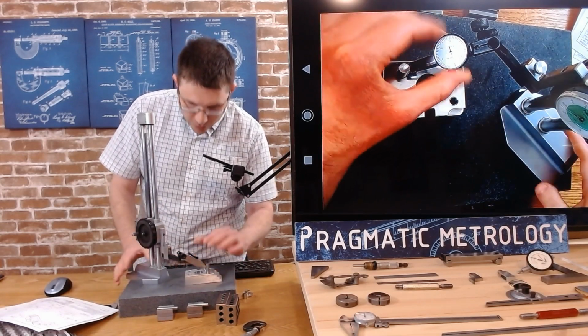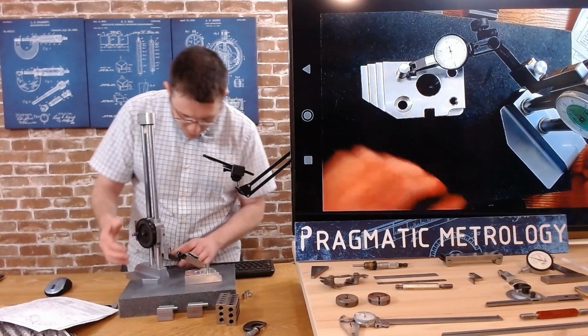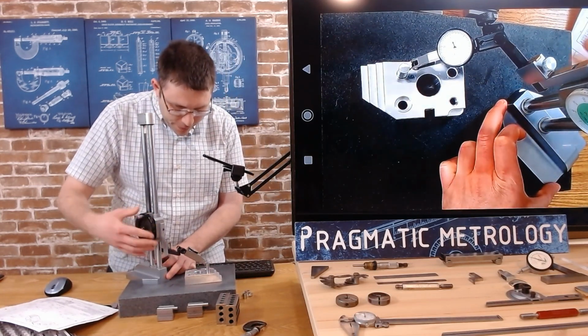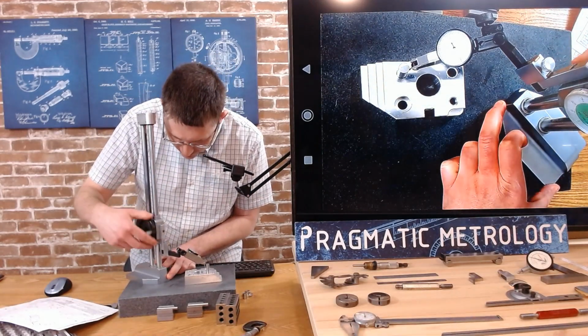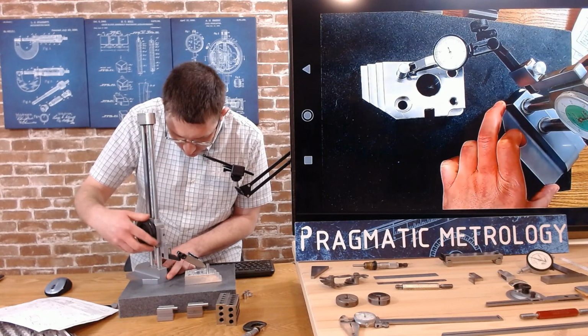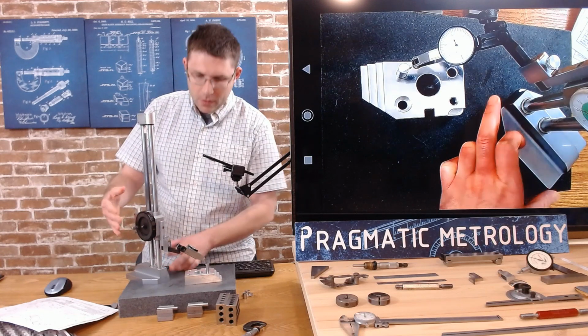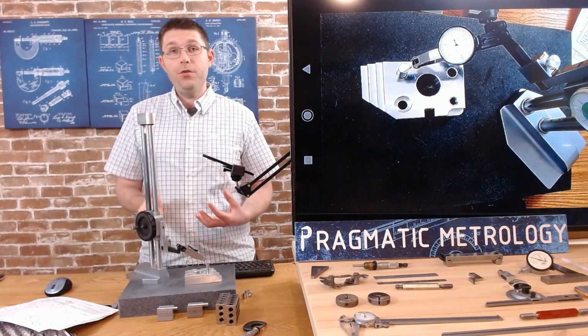And this is a little bit tricky because you have to be able to do this without bumping the indicator. But I'm going to zero my pin at the bottom, and then I'm going to run up the length of the pin, and I'm going to look for indicator movement. And I saw about a 1/2 thousandths from top to bottom. If I go back down, I'm getting a repeatable measurement of about a 1/2 thousandths along the length of that pin. Now you don't have to use the pin.